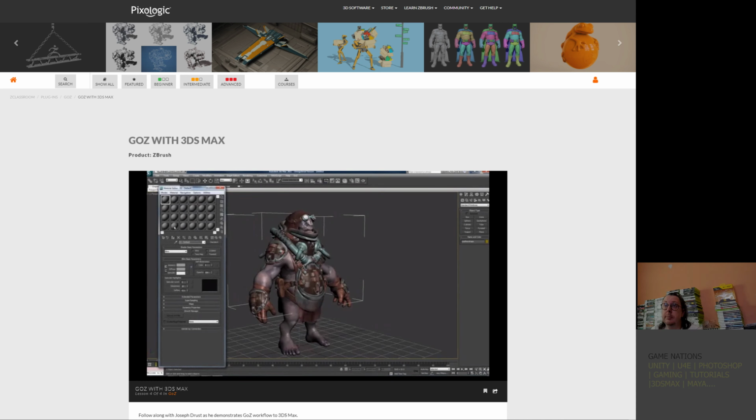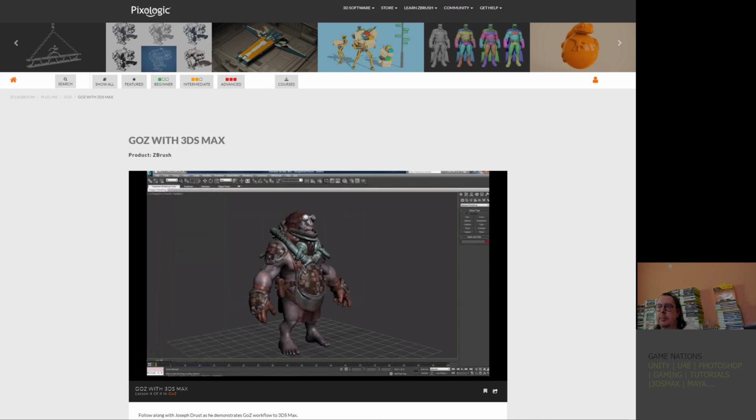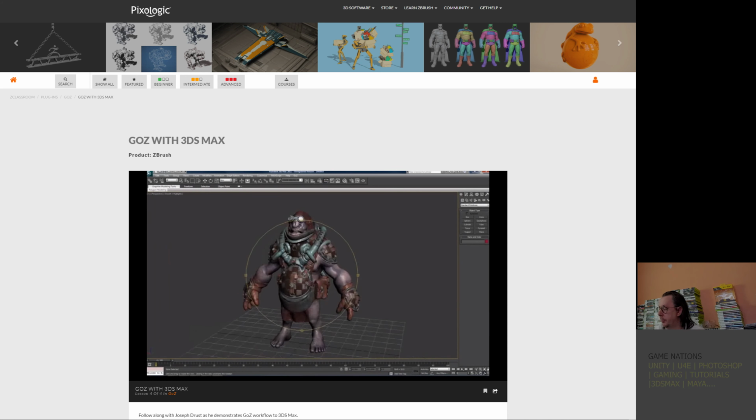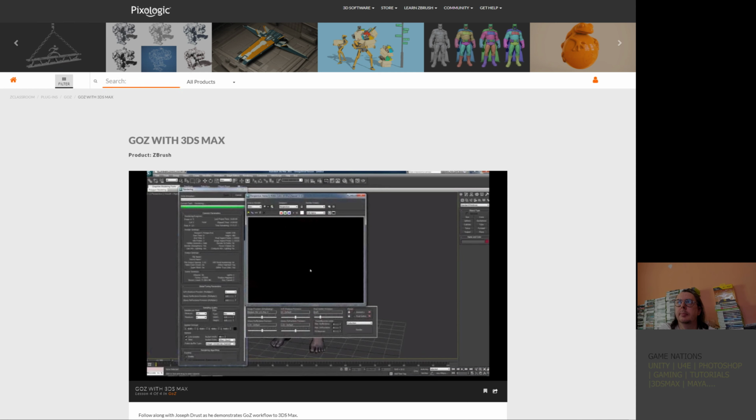If you go to the material editor again, you can now pick any different pieces of the subtool, and you'll see they all have the shell materials on them with the same kind of setup as before, with the maps and the displacement plugged in with the displacement values already set. So now we've just taken our entire 25 subtool mesh and threw it right into Max with one click of a button. You hit the render window again, and you'll see that it'll render the entire scene with displacement maps.